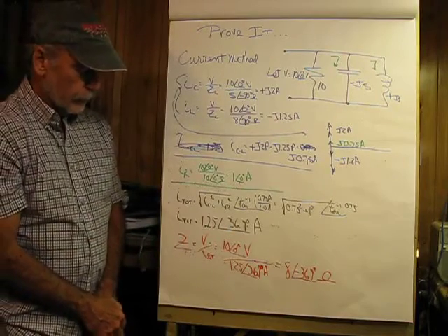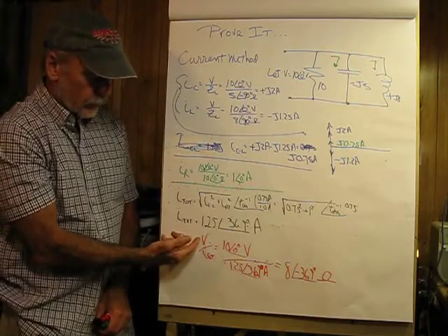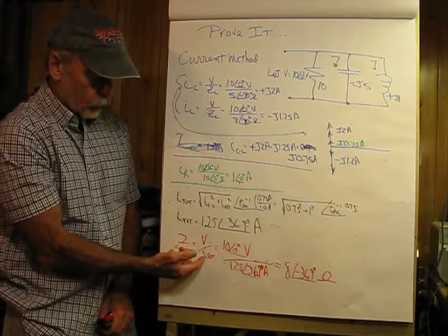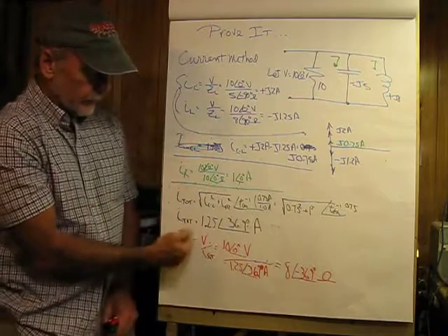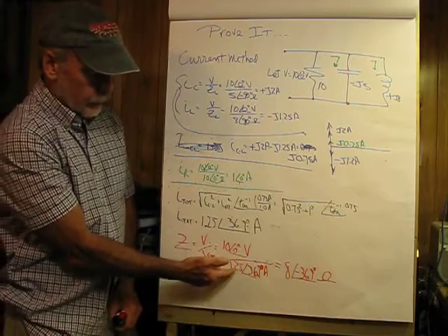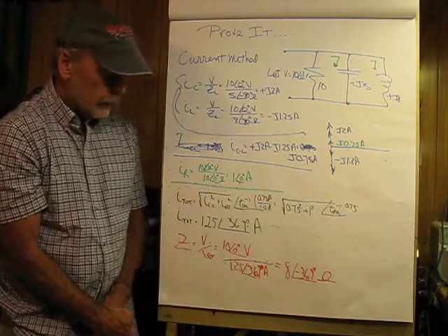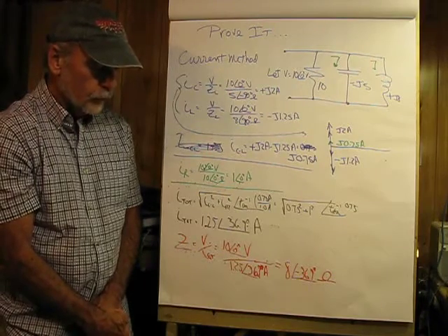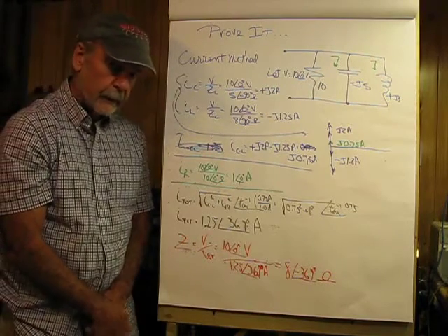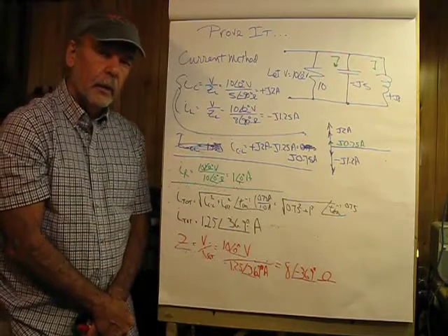And finally, for our sanity check, we find the impedance. I'm going to let V divided by I total and see what that gives us. If we take 10 at 0 and divide that by our I total here, we end up with an impedance of 8 at negative 36.9 degrees ohms, which is exactly what we had before when we found the impedance by using the admittance.